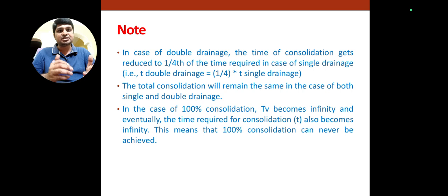The total consolidation remains the same in case of both single and double drainage. This is very important. So whether you take a single drainage path or a double drainage path, the total consolidation remains the same in both cases. Finally, for 100% consolidation, the time required for consolidation, t, becomes infinity.